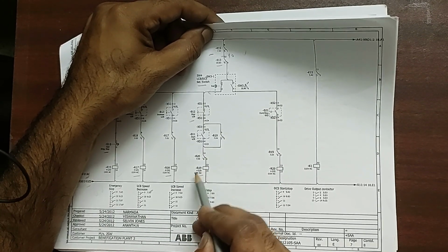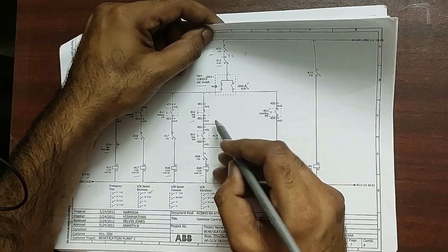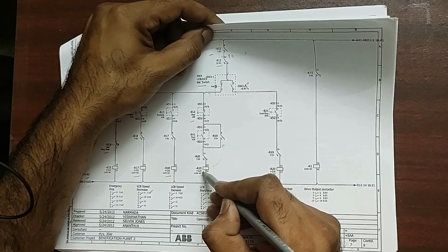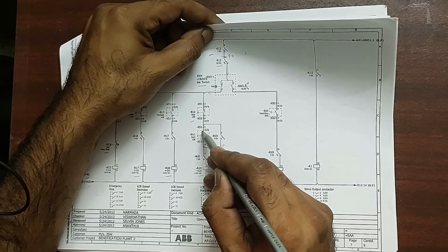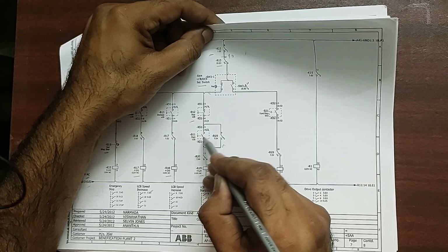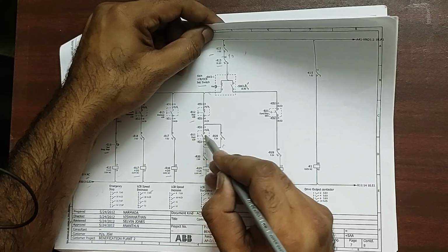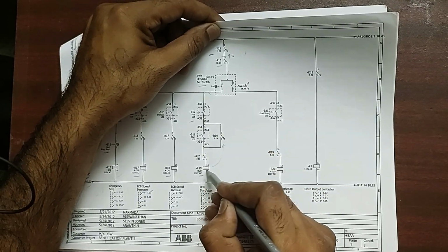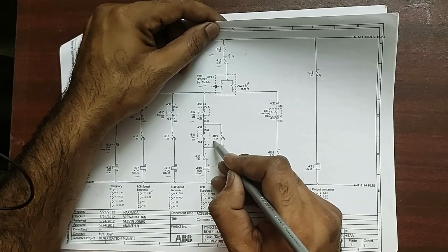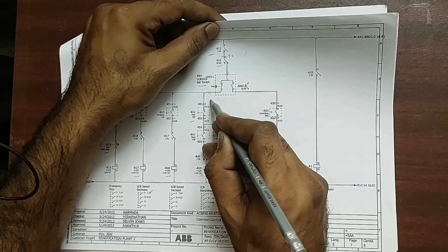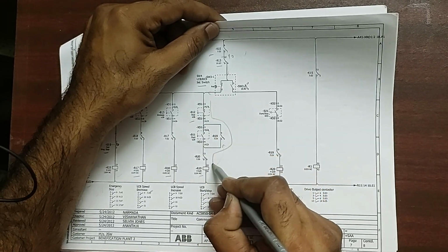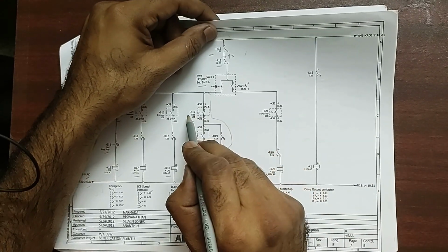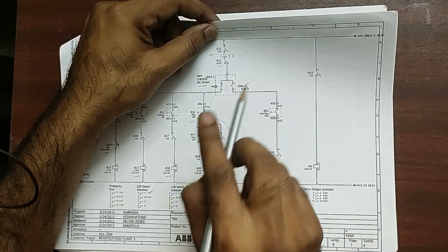Once R19 is picked, here you can see one of the terminals is being used, NO NC contact, R19 relay. Once pressed, the button will come back to its original position, that is it will remain open, but for a fraction of time 110 volt will come here, and later it will get the supply through this NC, and 110 will come from this point. 110 will travel like this and the button will remain open. There is no use.